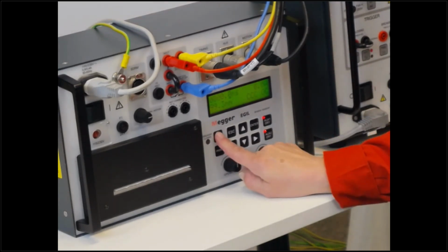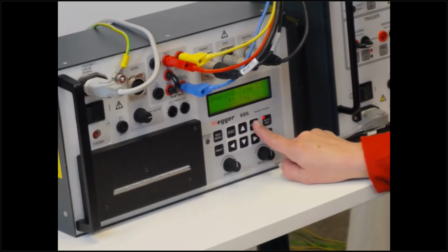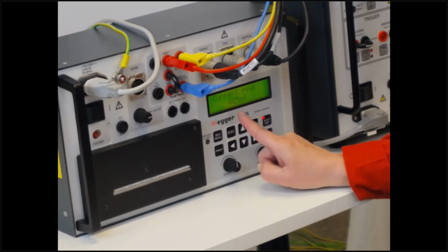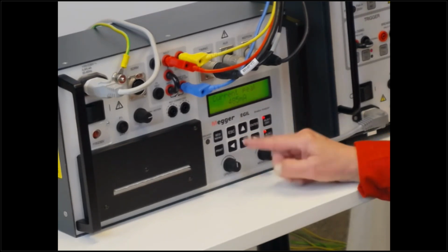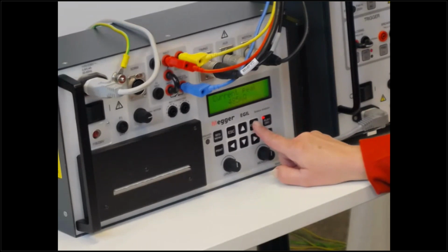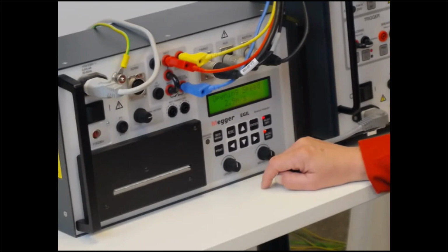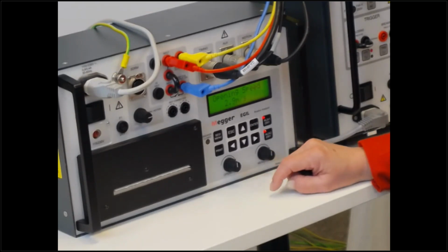I go back to the result menu on the display, and the opening times were 55.1, 55.7, and 55.5 milliseconds. So the phase difference was 0.6 milliseconds. And the current for the open is higher, just because of different coils. So that one is 485 milliamps. And stroke 100, and speed was 2.9 milliseconds.